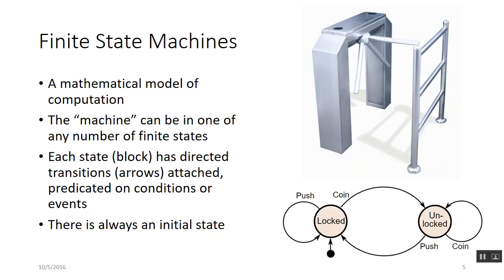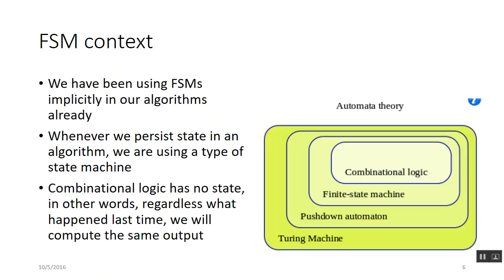But the really cool thing about Stateflow is that's how you create state machines. You just draw a state chart. And so you can make extremely complex logic and update it and understand it a lot more intuitively as compared to writing code or making a Simulink model or something else. And it can interact with all that stuff. So, yeah, there's always an initial state. They're directed arrows. So we already said all that stuff.